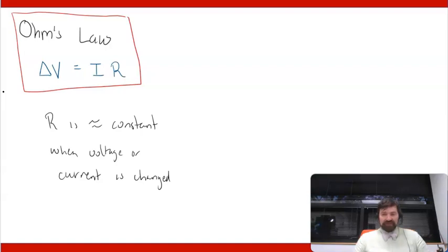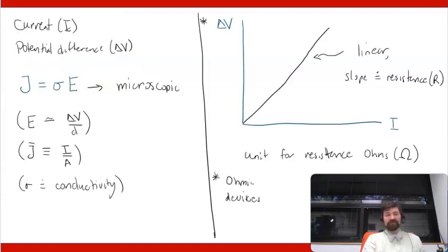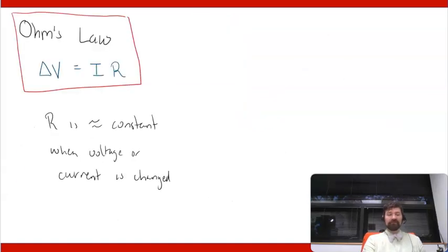I will talk about that a little bit more in depth in a separate video. It essentially depends upon a term called resistivity, which is the reciprocal of conductivity. So resistivity rho is equal to 1 over the conductivity. And actually, it's usually the resistivity that we measure for ohmic materials anyway.